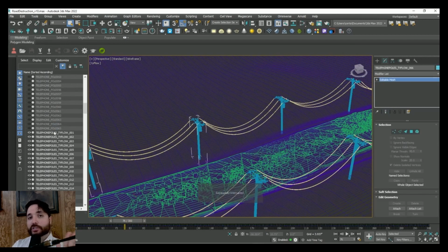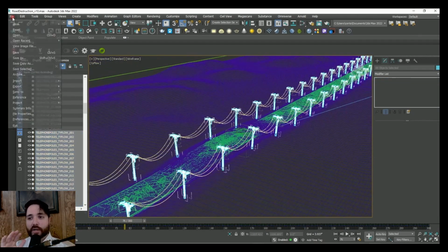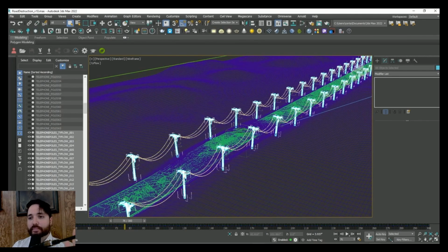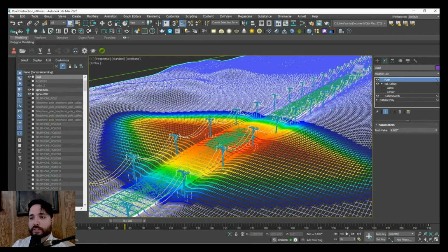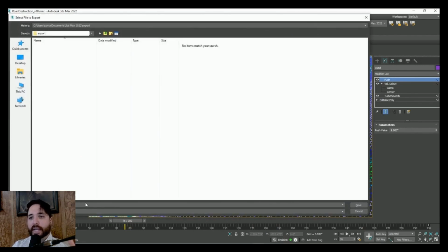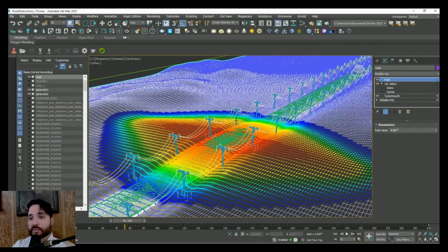And then by adding a surface test operator, we can test for proximity to the other telephone poles and then disable and bind any particles that are within a certain threshold. That way, when the gravity force is applied, the spline particles then hang down like a rope with their endpoints still attached to the telephone poles.